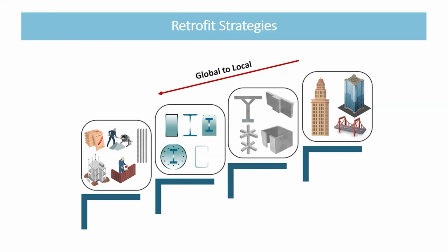And there are so many available options, for example BRBs, external frames, and so many dampers, even isolators. In the Philippines now, a lot of buildings are finding that just by cutting the whole floor at one level and putting in isolators, it fixes every problem in all of the floors above, because you reduce the demand completely. So there's no need to do anything else. That's the quick fix for the whole structure at one time. So that's what we should be thinking about.